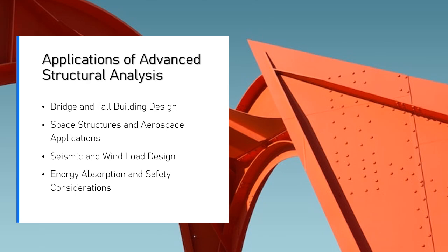For buildings located in seismic regions, base isolators are designed to absorb and dissipate energy from earthquake ground motions. Advanced analysis. Using tools like finite element analysis, FEA, engineers simulate the building's performance with base isolation under seismic loading. The isolators are designed with materials like rubber or steel, often combined with viscous dampers to enhance energy dissipation.